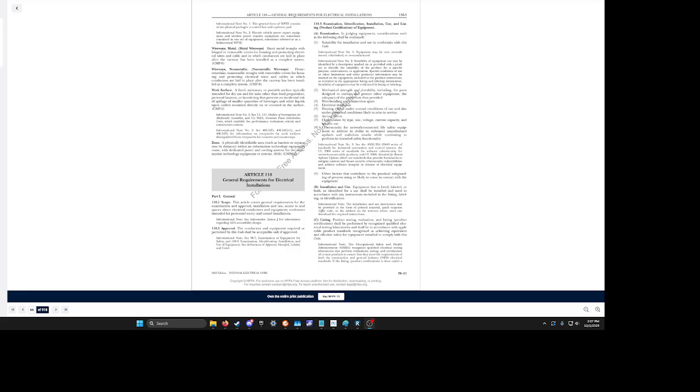AHJ saying otherwise. Listing. Product testing, evaluation, and listing, product certification, shall be performed by recognized qualified electrical testing laboratories and shall be in accordance with applicable product standards recognized as achieving equivalent and effective safety for equipment installed to comply with this code. So, again, if something is listed, that means it has been tested by a company and is properly certified to be good enough to use.